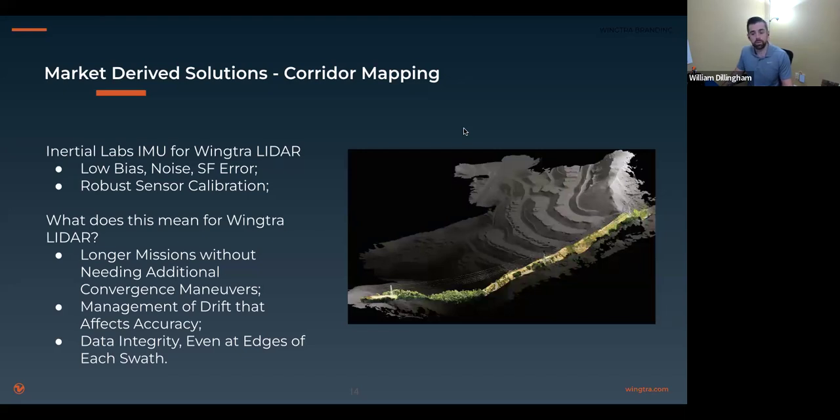You've got better reliability of your trajectory estimation. That ends up trickling down into the final deliverable, but really the starting point for most of you, which is the point cloud. And having that better inertial inside means that you get to use not just the point that you're scanning right over, but also the full swath width of the Wingtra LiDAR, which is right about 90 degrees.